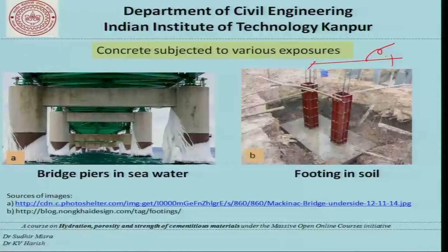Continuing further, we have concrete used in footings in soils, and that is where we have groundwater kind of attack as far as the concrete is concerned, and these footings are also carrying a certain amount of reinforcement, and we need to ensure that the reinforcement is appropriately protected. It is not only the sulfates, but at times the groundwater could also contain chlorides.